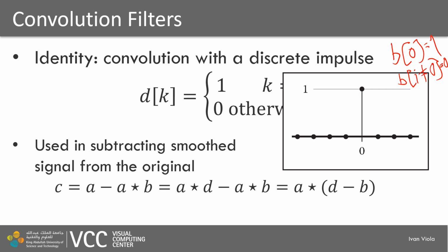So this filter kernel is everywhere 0, only at 0 it is equal to 1. And if we are filtering our input signal with such a filter, we will basically just be multiplying the currently processed central sample with 1, and all the other neighboring samples we will be weighting with 0. So it will be an identity transform.